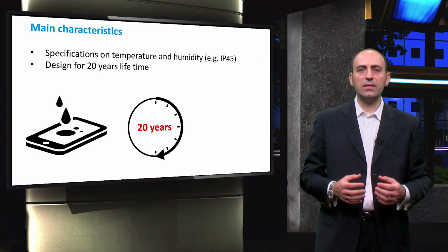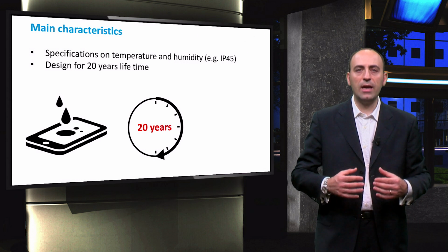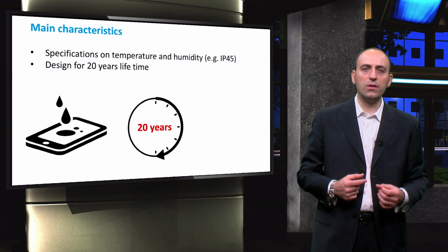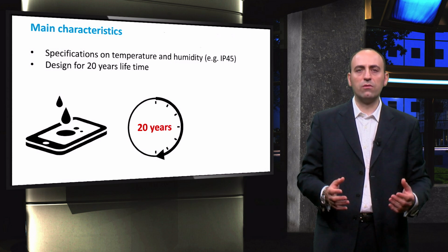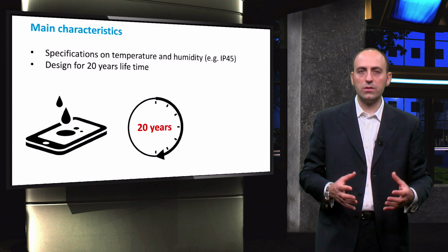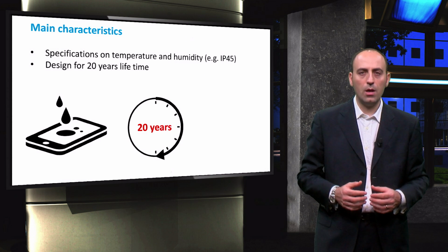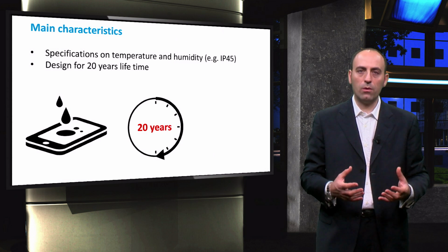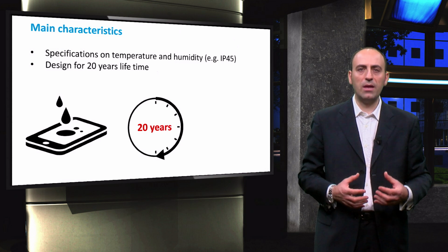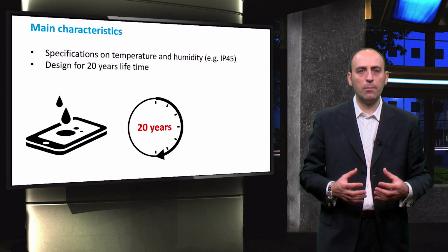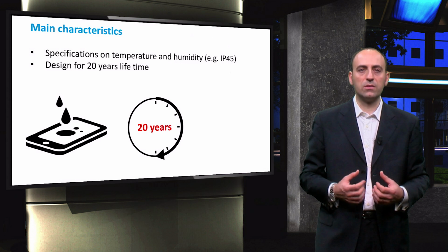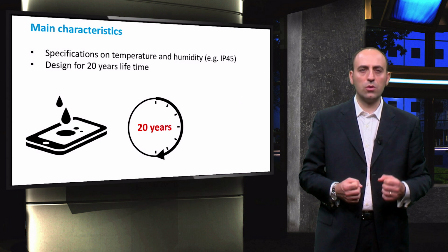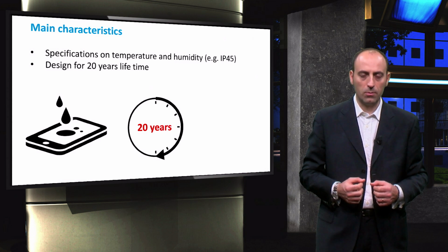Usually, the device has to be designed for a high ambient temperature and 20 years of operation, although most of the time brands offer warranties ranging around 15 years. Nowadays, these components are becoming more and more reliable, but power electronics and batteries still remain the most fragile part when it comes to maintenance, while PV panels are usually the sturdiest part of the PV system.